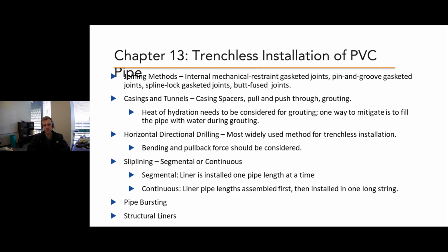The same goes if you're doing open cut and using flowable fill or encasing pipe in concrete. You do want to take into consideration the temperatures that heat of hydration can cause. Horizontal directional drilling is another common method for trenchless installation. Really the main consideration when using PVC for HDD is the bending and pullback forces.